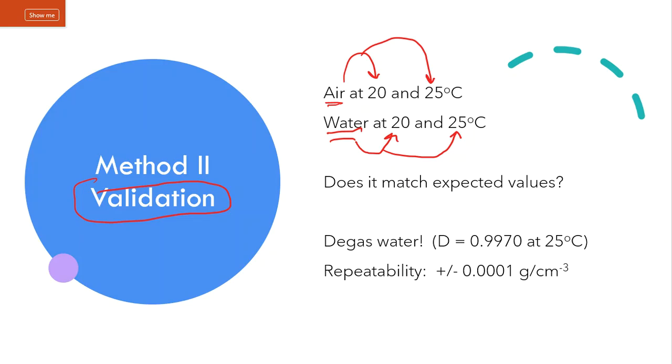All right. Finally, you want to make sure that the water is also degassed, and degassed water samples, CO2, always a problem. So by heating that up a little bit, you're driving off all of the CO2, because that gas can create bubbles, and bubbles take up space, and space is going to be a problem.